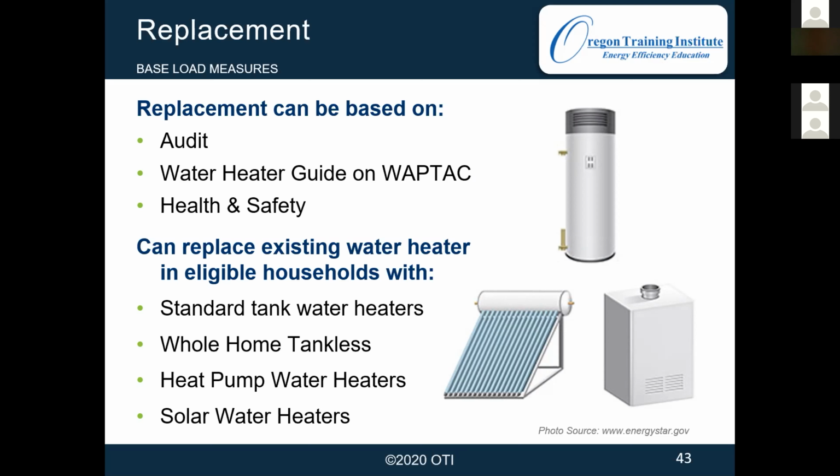But we've got, for electric, we've got heat pump water heaters, and that can save a ton of energy. They're going to use half or even less than an electric water heater. But they are big, and some of them do cool the room that they're in. So you have to have a location to put a heat pump water heater that's big enough, and you don't mind it being air conditioned, essentially. So garage can be a good place for them. And they definitely do save a lot of energy.